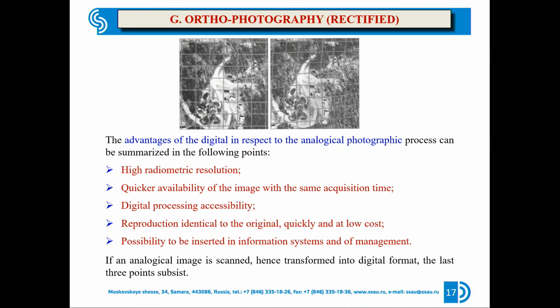So, generally we get that type of photograph, meaning the pixel is not at the exact location and has some movement. When we rectify it, that is called an orthophotograph. In satellite remote sensing, when we remove errors, that is called rectification: we use topographic maps and GPS points and then correct the image. And once our satellite image is rectified, later on another satellite image can be rectified with the same previously rectified image, and that process is called registration.